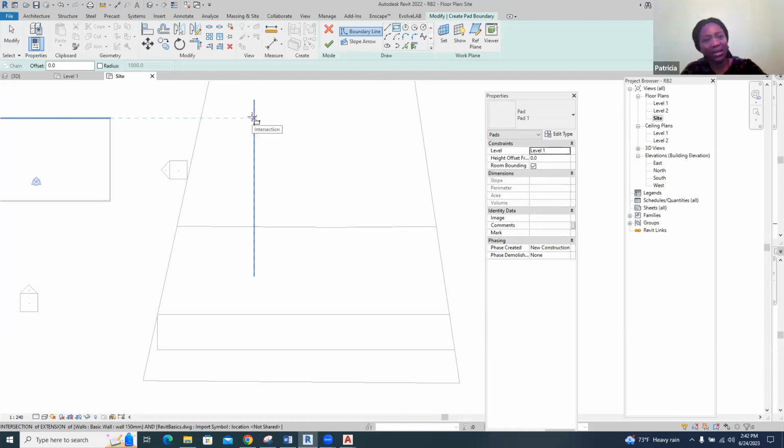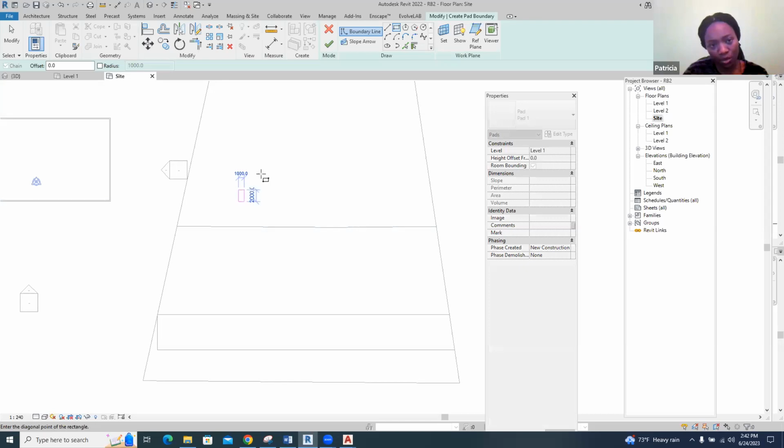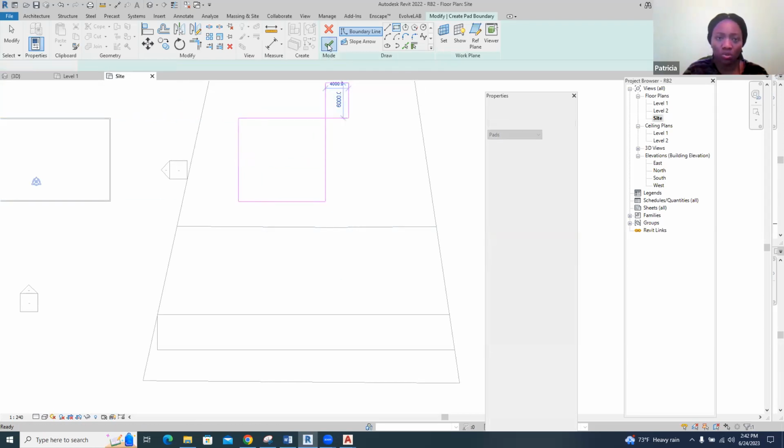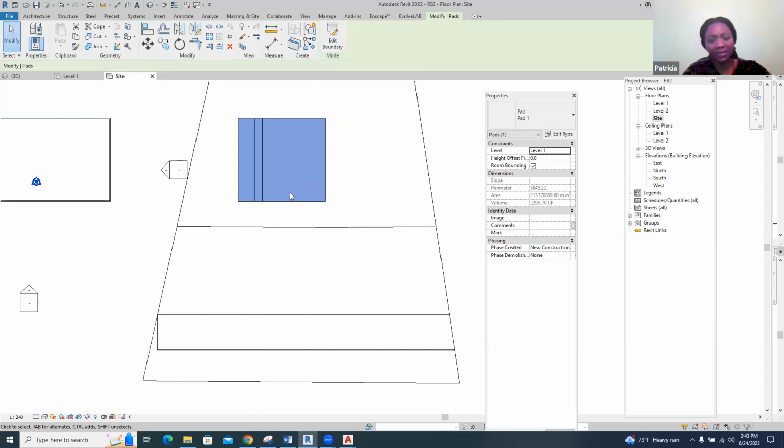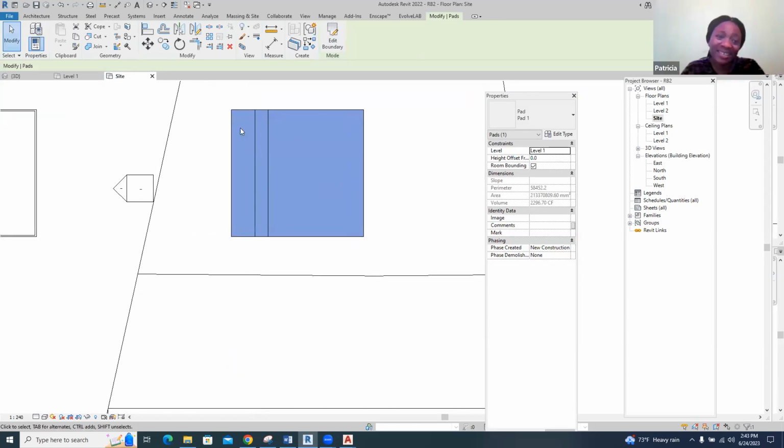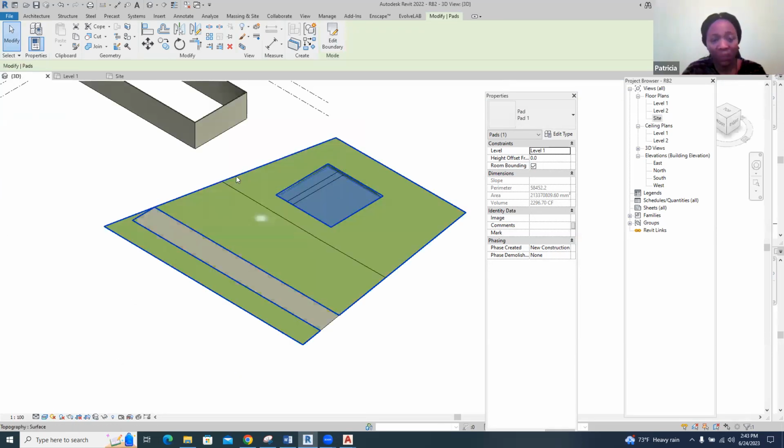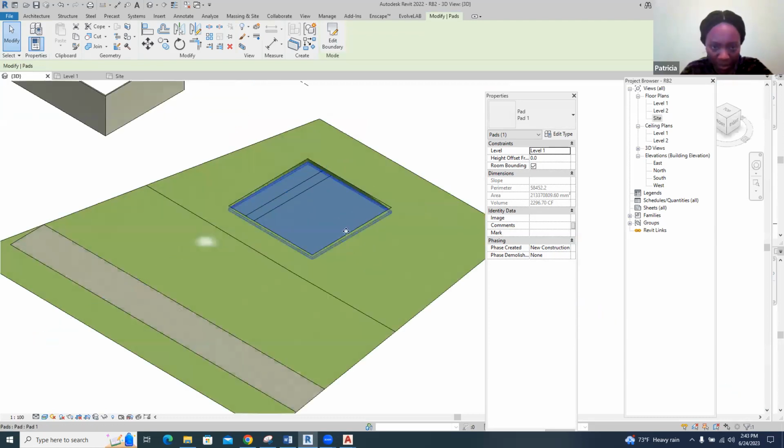So let's say you want to go align with the old line. You see that it will show you, okay, you're aligned to something, as you're moving, showing you the relationship between things there. So it makes it easier for you to just settle on the design that you want. So it's showing me that I'm aligned to the top and the bottom of that other house that I put. And I click. So once we're done, we check the mark, we have our building pad there. And you see that it's aligning to the terrain, the topography of that site that we already made.